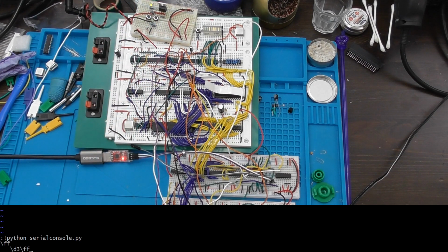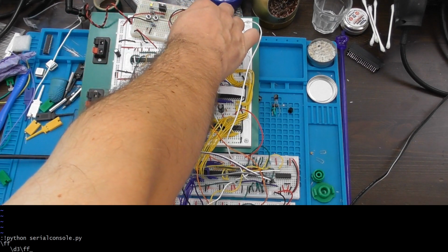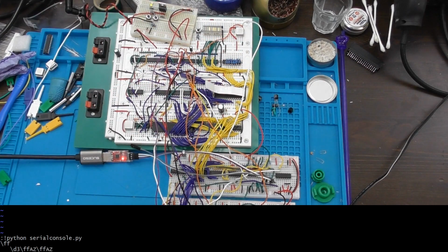So that doesn't look quite right, we've got some junk on the terminal there. Let's give it a reset and see whether that works any better. And yeah, that looks better, that's got AZ on it now. I don't know exactly what happened there, it may have been some glitches on the transmit data line or something like that during the power on. Maybe it's due to my power distribution not being great. I'm not sure about that. Maybe that's something to debug later, but it seems to be working after a reset, so let's try typing some characters and see what happens.